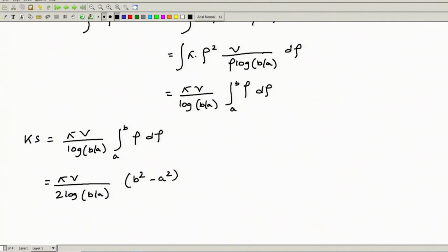Now this magnetic loop is equivalent to an electric dipole if we make the substitution IL equals minus j omega epsilon Ks. In place of Ks, we can substitute this value and then eventually find all the fields. So this is all for today. Thank you.